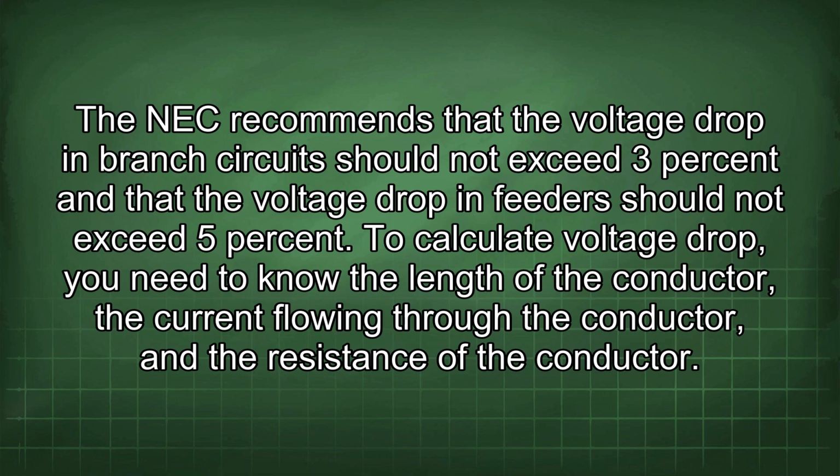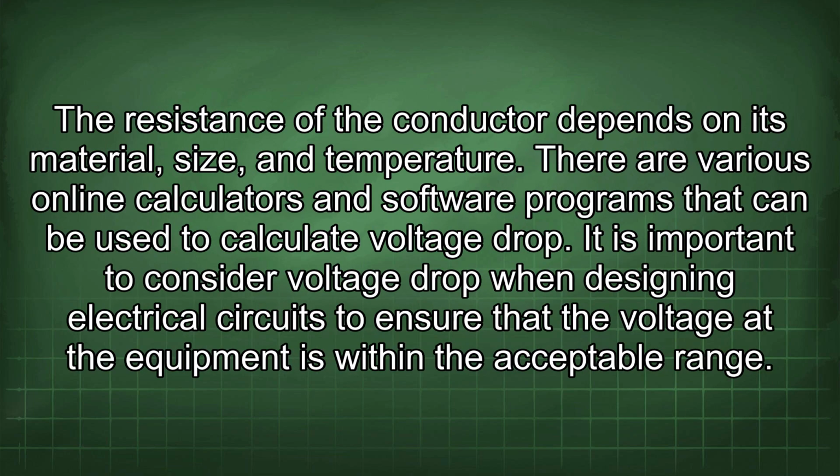To calculate voltage drop, you need to know the length of the conductor, the current flowing through the conductor, and the resistance of the conductor. The resistance of the conductor depends on its material, size, and temperature. There are various online calculators and software programs that can be used to calculate voltage drop. It is important to consider voltage drop when designing electrical circuits to ensure that the voltage at the equipment is within the acceptable range.